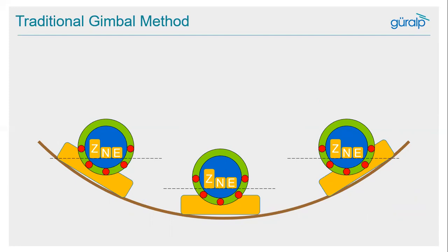And inside we have the seismometer in blue with the components again in yellow. Now the seismometer is allowed to freely rotate depending on which way gravity is. And the red balls along the outside allow it to rotate inside the green sphere. As we vary the angle along the brown line, the seismometer is allowed to tilt. Usually these gimbals have a maximum tilt tolerance, and they also impart inherent noise into the instrument, which we cannot easily get rid of.